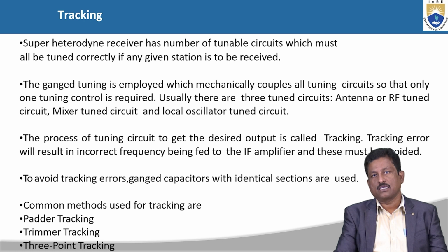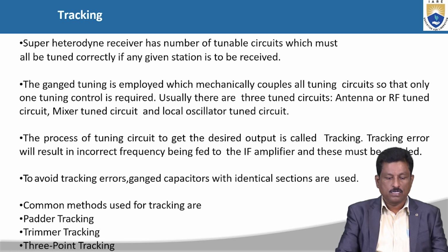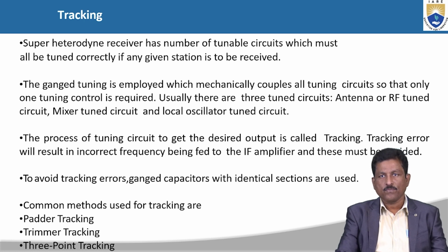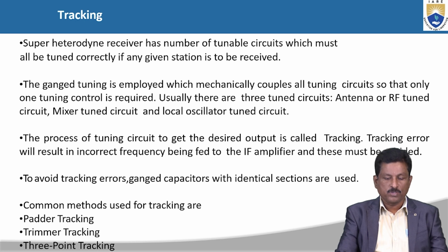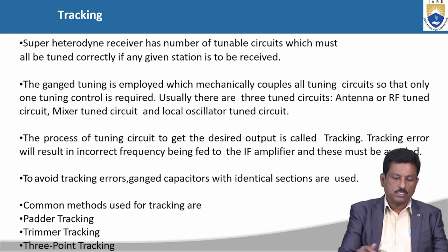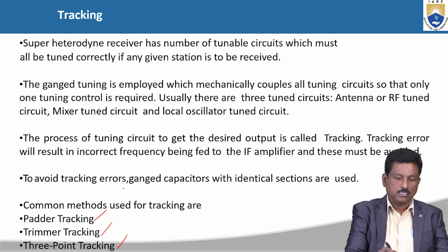Then tracking: we have trimmer tracking, three-point tracking, and padder tracking. Tracking means that, without error, the received signal frequency can be tracked to the desired value. There are three commonly used tracking methods: padder tracking, trimmer tracking, and three-point tracking.